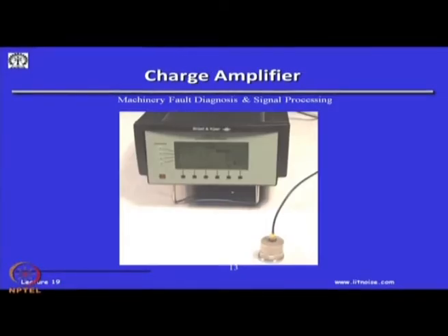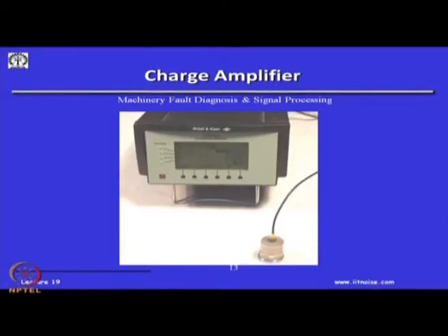And this is essentially a charge to voltage amplifier, and this is the accelerometer here, and this is the special cable I was mentioning, which reduces the triboelectric noise, and sometimes you will see the cables are costlier than the accelerometer itself, because if these cables are beating around, if they move, they are manufactured in such a way that there is so much reinforcing in the cable itself that the copper conductor inside hardly has any motion.